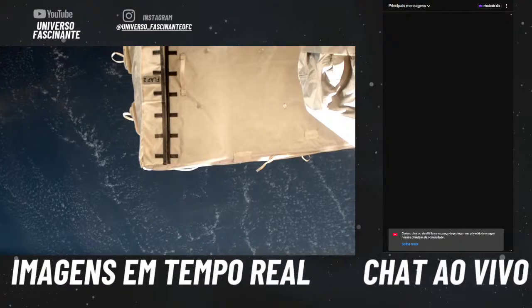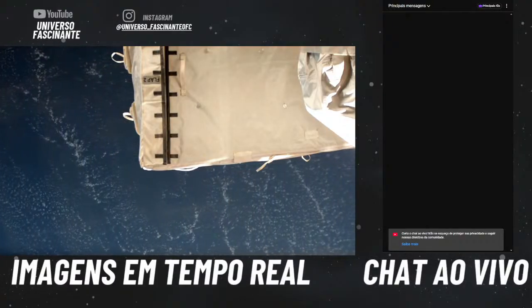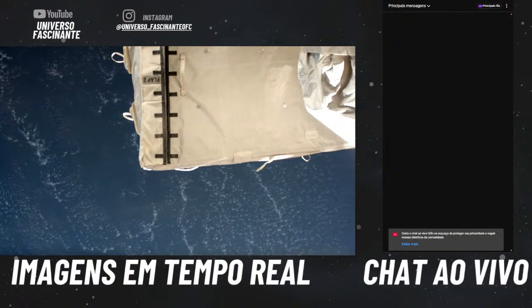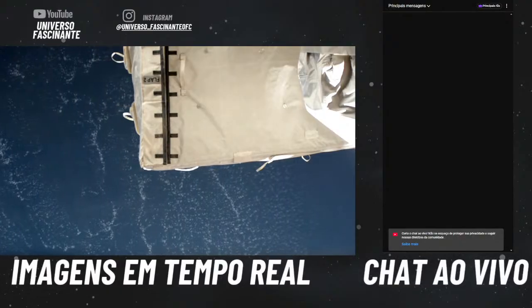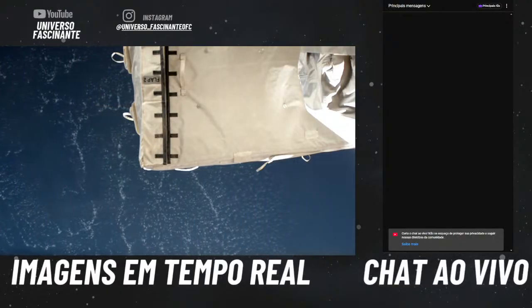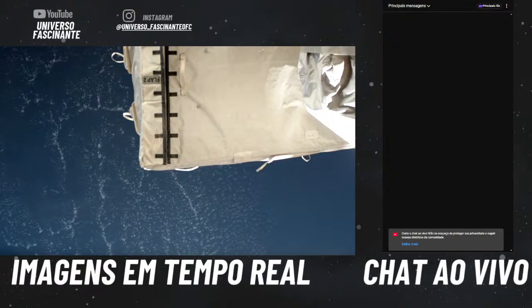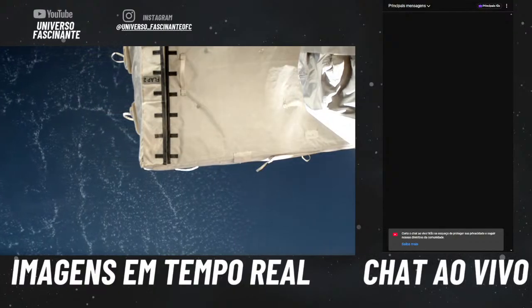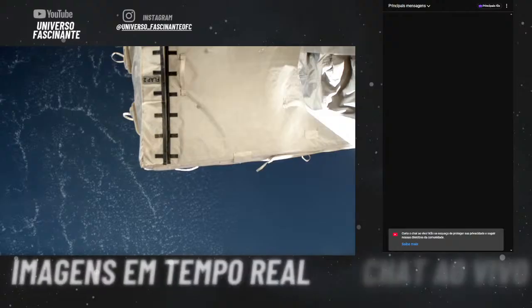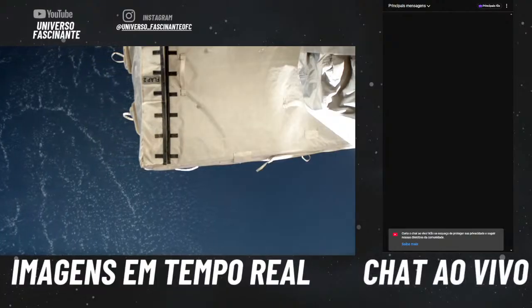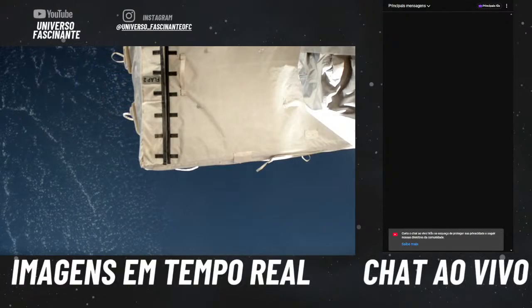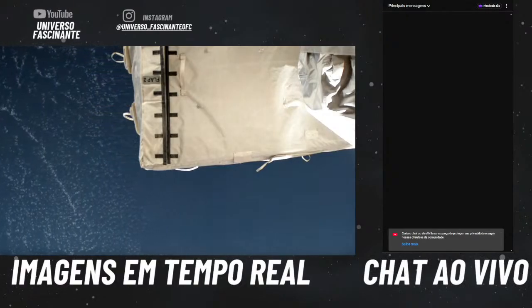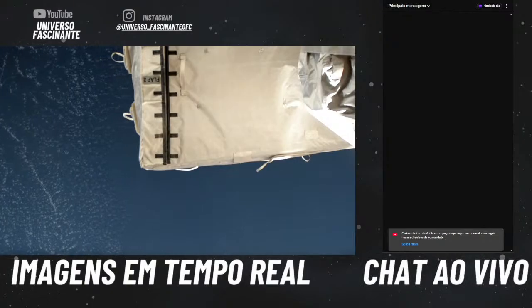You've seen, perhaps in past Soyuz landings, a white vapor emanating from the spacecraft. That is normal. That's a combination of hydrogen peroxide and oxygen venting into the air. The purpose of this is to safe the vehicle for landing. The search and recovery forces do not want hazardous gases to remain in those tanks when the soft landing thrusters fire just a second or two before touchdown. This way, the ground support team can approach the vehicle immediately without any concern for hazardous gases.